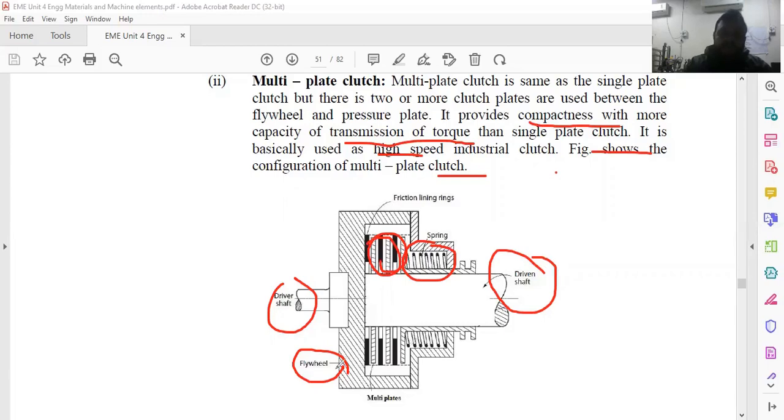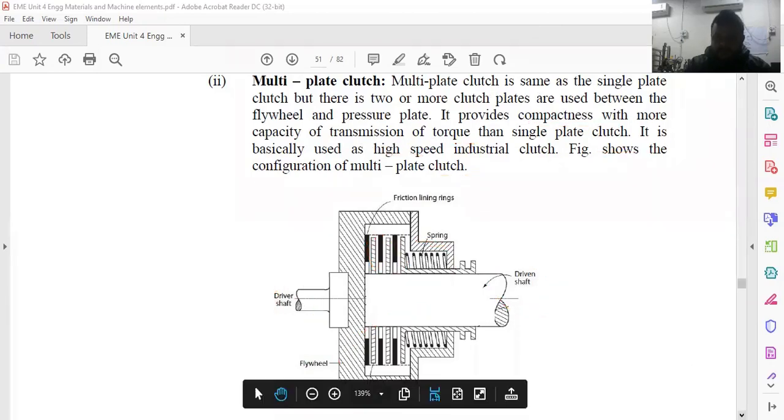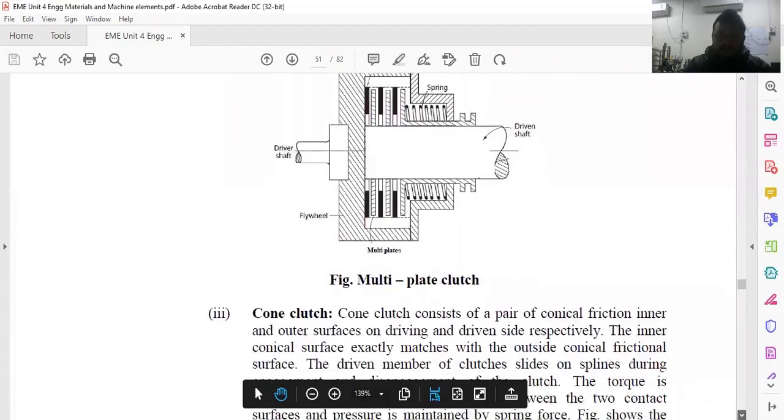So whenever power required is more, that can be released by the flywheel and provided to the driven shaft, that is already stored during the off peak hours. So flywheel is, we can put it as reservoir of the power, and it neutralizes the balance between the driver shaft and driven shaft. So flywheel itself is a mechanical element also. We can consider itself a mechanical element with respect to this. So this is about the multi-plate clutch, where you can easily see the multi-plates.